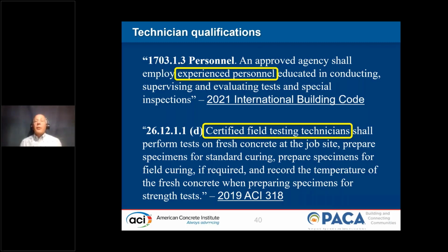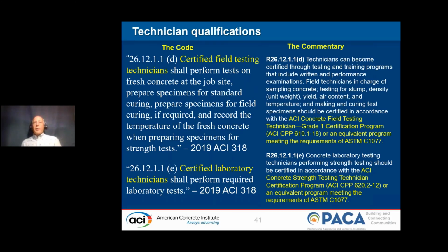ICC says experienced personnel need to be employed by the testing agency. Fortunately, in ACI 318, the documents that make up the basis of that code say the technicians both in the field and the lab need to be certified. So here is that code. And of course, you've got the code on one side of the page and the commentary on the other. The code is in mandatory language. The commentary kind of explains a little further what needs to be done. And it says that the technicians need to be certified according to requirements for ASTM C1077.